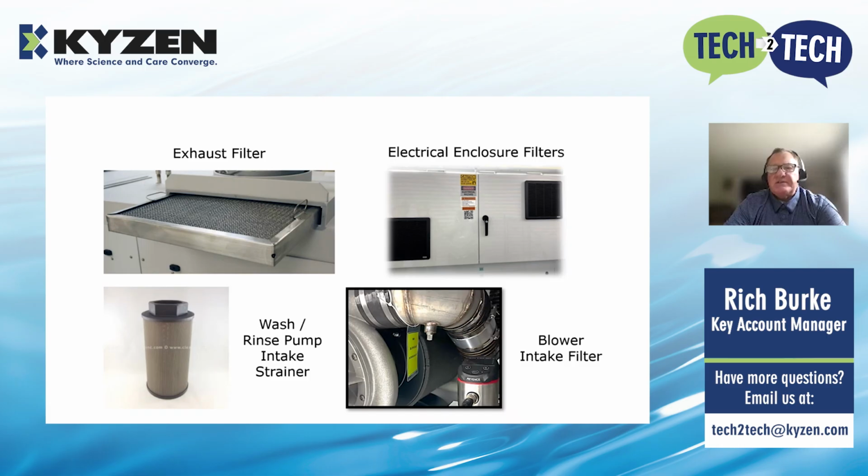We can have catch screens that capture gross contaminants prior to getting it back into the washer rinse tank. Those should be checked. We can also have bag or cartridge filters within our system. So, there's many different places where we might find filters and strainers and catch screens. But again, just follow the instructions from our supplier in terms of their location, when and how we should either service them or replace those components.